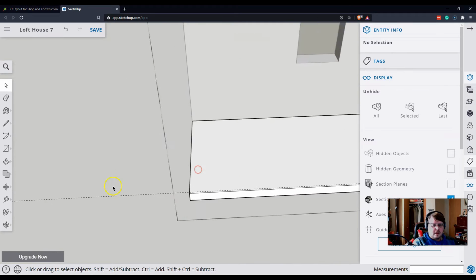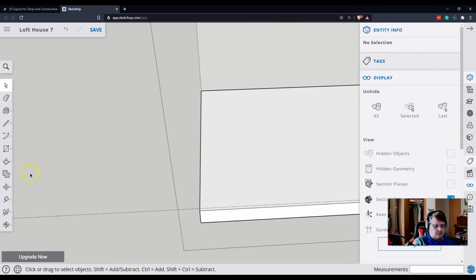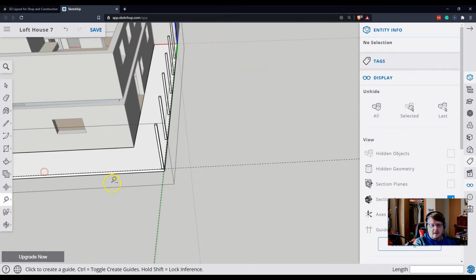So let's do the same thing here. Let's create a spot for this to go. We're going to tape measure in here 1 inch. When you use slash instead of times for doing an array, it's a different kind of array. We're saying fill this with X number, evenly spaced. So I do 6 divided by instead of 6 times. So let's try this one more time.